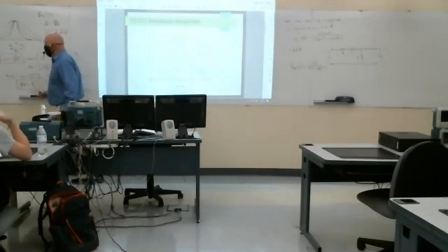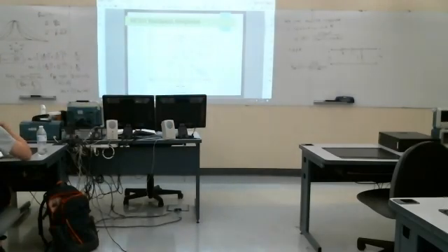And this is a little tough to figure out. You can figure out what's going on at low and high frequencies. At low frequencies, it's 0 because of the S in the numerator. At high frequencies, you're going to have a 1 over S dependence, right? This term would dominate. You have a 1 over S behavior, but that goes to 0 as S becomes infinitely large. So the question is, what happens in the middle somewhere? And that's where the resonant frequency comes into play.